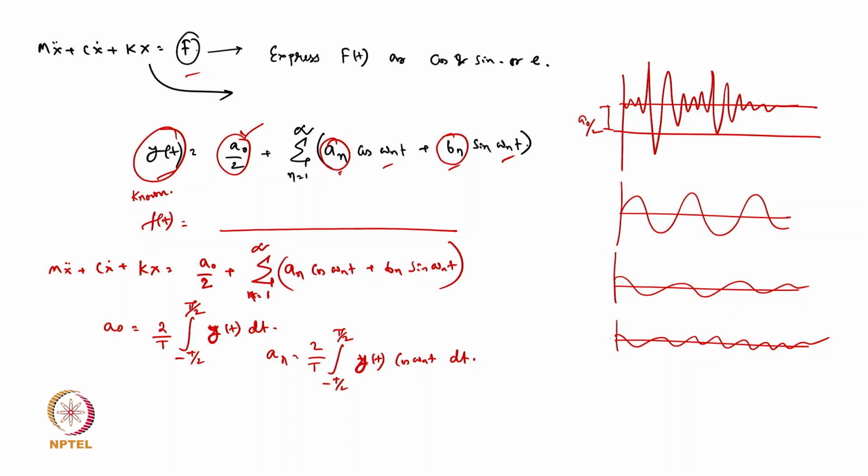We really don't know how it is made, but we can express this function as the summation of several harmonic functions. We can calculate the amplitude and the phase of each harmonic function, and if we sum all of those, we will recapture our original signal. That technique is known as the Fourier transformation.